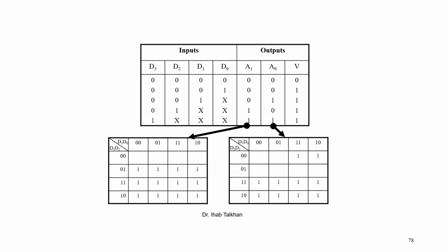But actually here, as you can see in this table, we have a double 0, 0. Double 0, 0 means that you have a double coding system, and this should never happen. They cannot have a double coding system, so you have to differentiate between the 0, 0 by using the V output. The V output, V stands for valid or not.